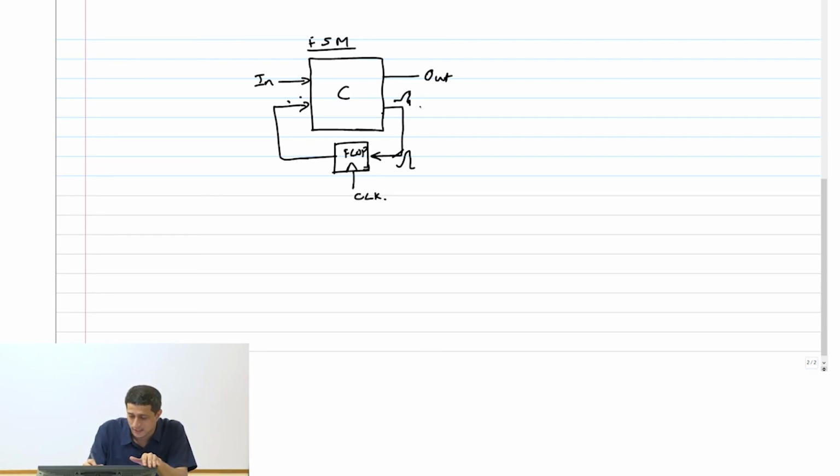Okay, this is a state S, this is a state S1. So this is how you design counters, you do everything, right? So the need for sequential elements we have actually seen even in a digital design course earlier. I just wanted to point out that this flop is nothing but a delay element, but a programmable delay element. You can give how much delay you want.